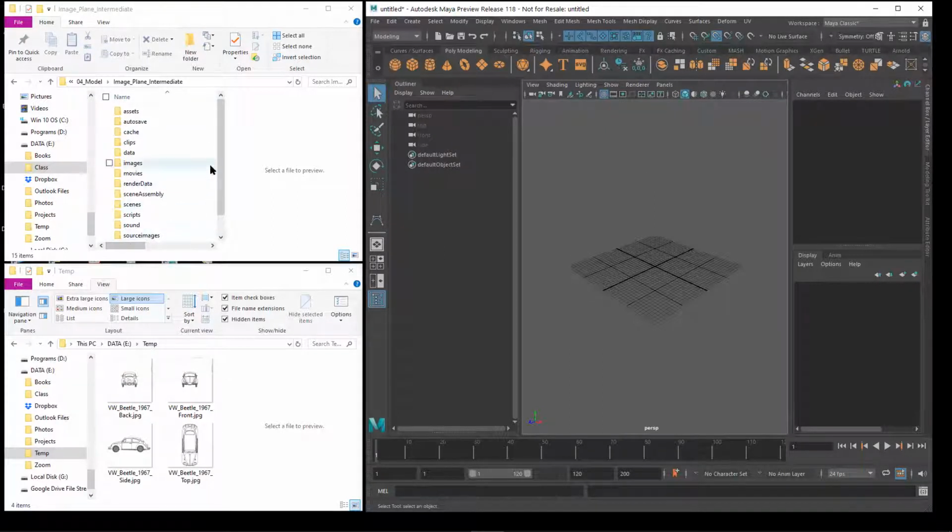In there, that's where you're going to find your scenes directory, where you would save a file. But this is the directory you want to put images into that you're going to be using in Maya. It's called source images. Now remember that, it's going to be really important. These two directories are going to be very important to you right now. Scenes is where all your geometry is going to be. And source images, if you're bringing some kind of files in, like some drawings or some images or some reference for texture maps. Later on, when you start putting color on your objects, like if you want to make something look like stone, you're going to bring a stone photograph and drop it into this directory here.